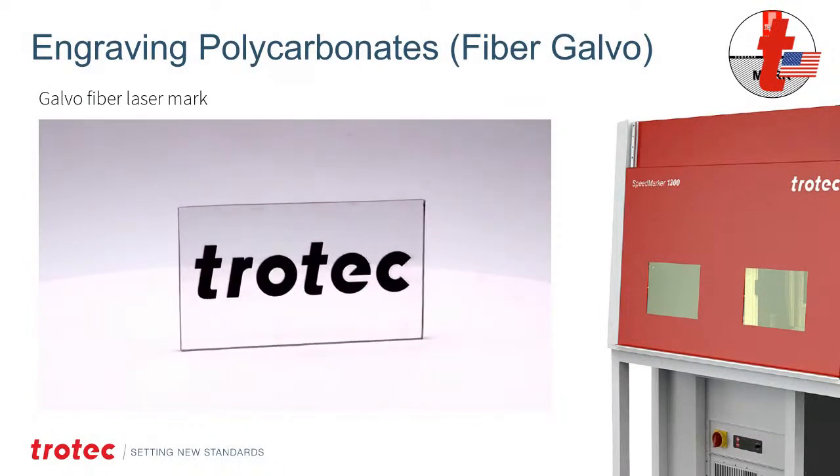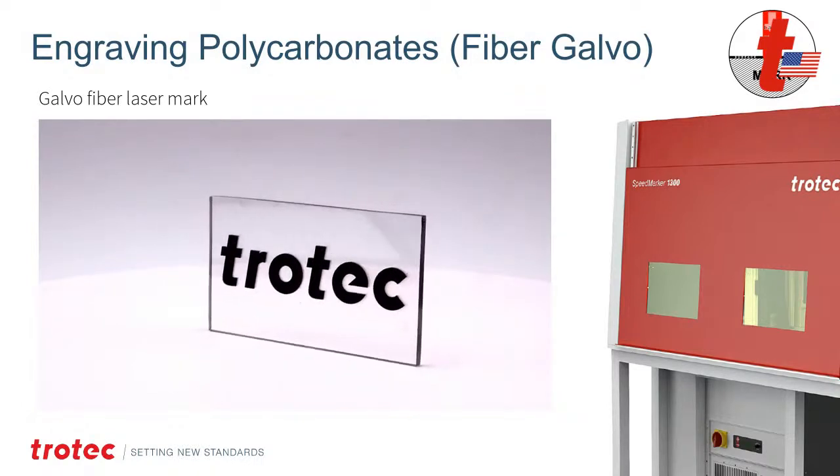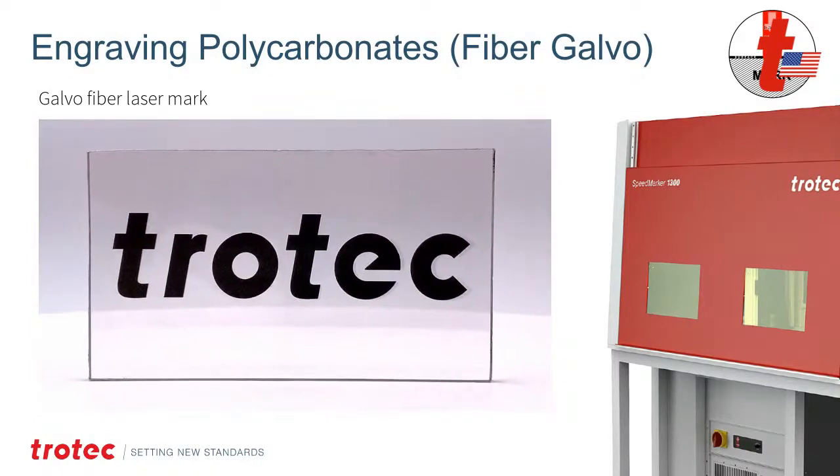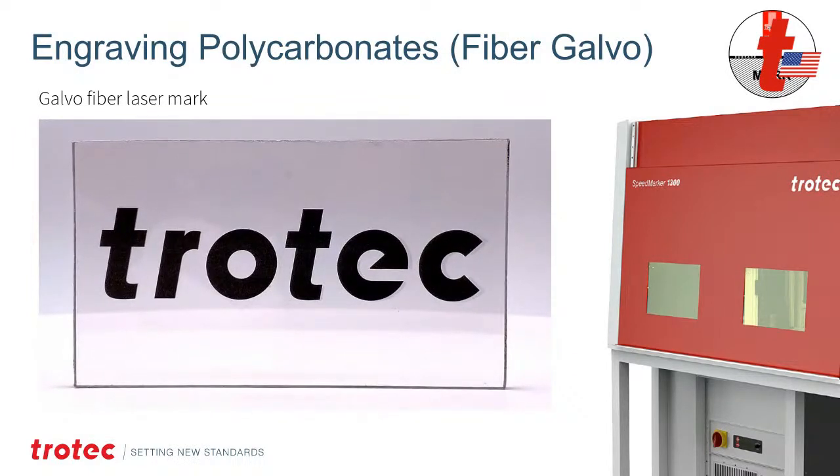So this process is great if you do want to do a lot of marking on something like a polycarbonate. Galvo fiber laser is your best. Flatbed fiber will definitely work. CO2 will produce contrast, but as you saw earlier, it is kind of a yellow effect. And the cutting capability is poor at best, if you will.